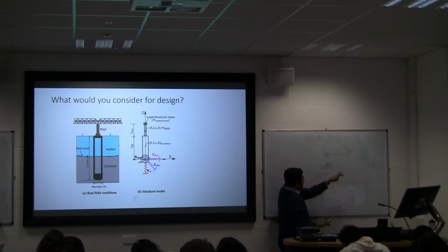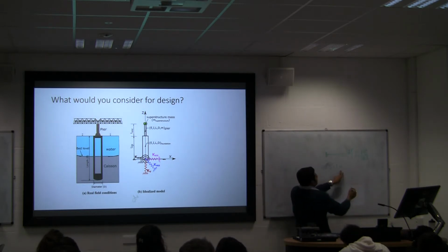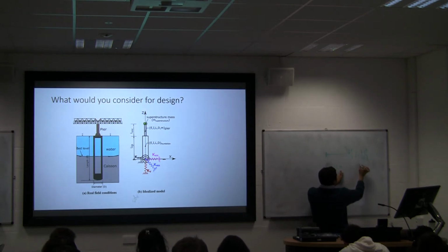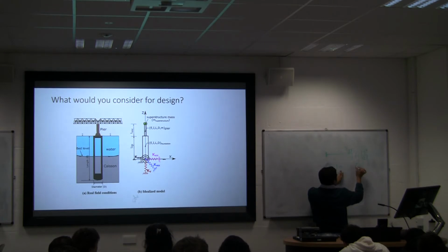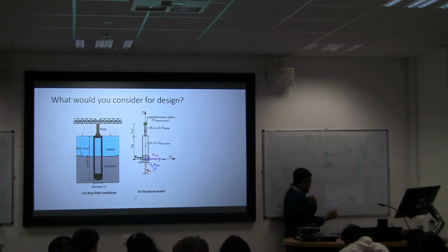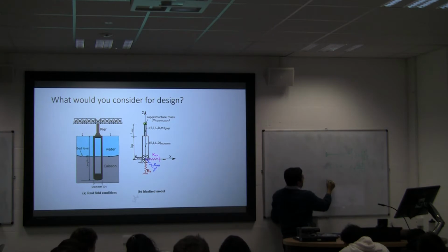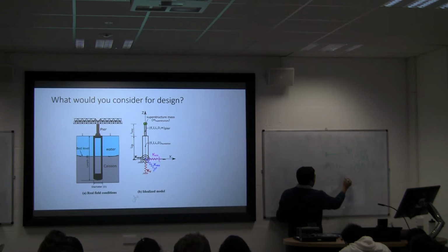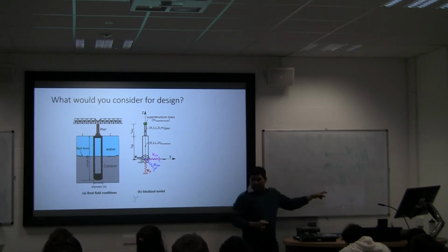Therefore when delta is 1, P is given by 3EI by L cubed. Therefore, the lateral stiffness, the KHH term, is basically 3EI by L cubed. Yeah, we used this before, isn't it?